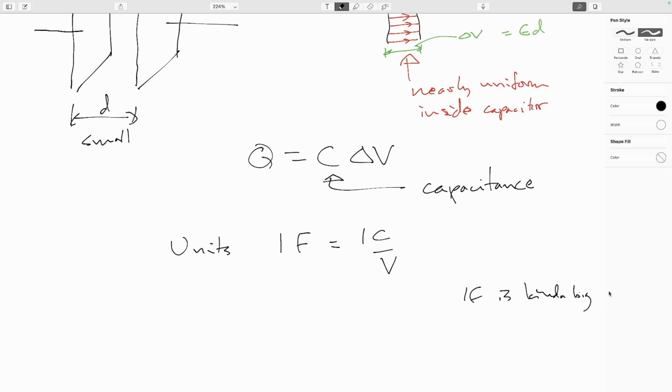It's not to say that you can't have a 1 farad capacitor. You totally can. And actually, you'll see on a lot of computer power supply boards, in order to prevent the computer from rebooting if, say, the dryer kicks on in the house and you have a momentary fluctuation of current throughout the house, they'll usually stick something like a half farad capacitor on there. But it's only designed to operate at fairly low voltages.